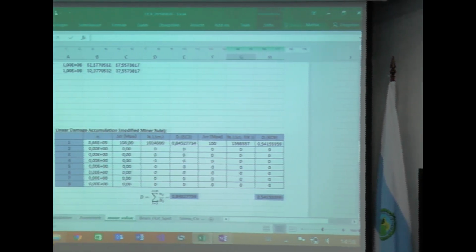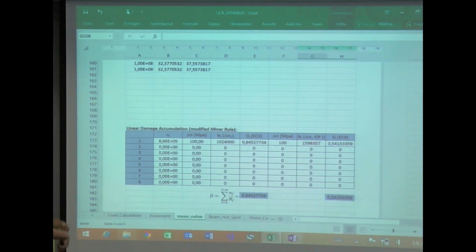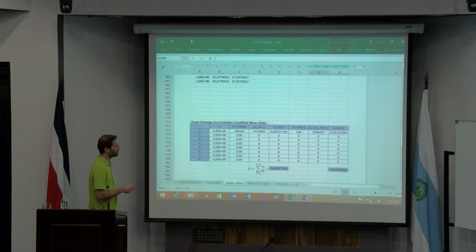And due to this, as you can see here, you move your SN curve upwards. Due to this, at the same stage, you can handle a higher amount of cycles. So instead of the 1.1 million times 24 over 24,000, around 1.6 million cycles.